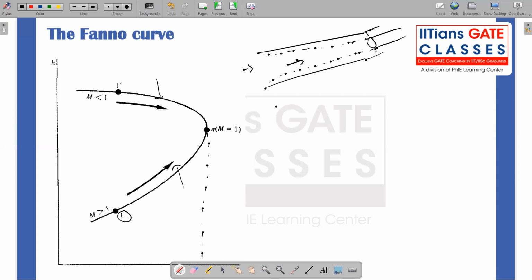More importantly, you have to remember that in a subsonic flow, the increase in length of the duct is going to increase the Mach number until it reaches the sonic condition. And again, in supersonic flow, the increase in duct length will decrease the Mach number, or decelerate the flow, and it reaches the sonic condition. After the sonic condition, further increase in duct length is not going to help. It stays at Mach number equal to 1. In reality, it is going to change the upstream condition and readjust the flow. So that's what happens in reality. But for a given upstream condition, there is a choke. After that, there is no effect of increase in length.